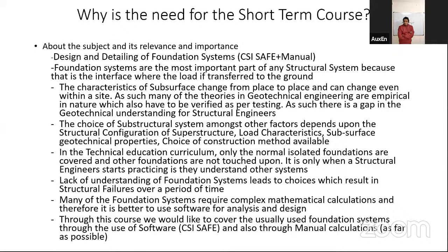All right. So the lack of understanding leads to structural failure, not overnight, but maybe after 5 or 6 years you see some deflections in your beams. Maybe you see some deflection in the slab. So the deflection may be at slab level, but the root cause may be deflection of footings, isn't it? You never know, and you never try to identify the failures. From the ground up, you may see that this failure is in a particular beam or in a particular column, but that failure may be the result of some foundation level failures, isn't it?